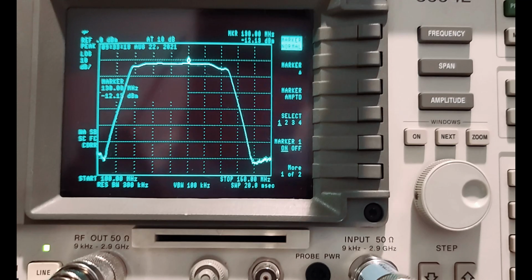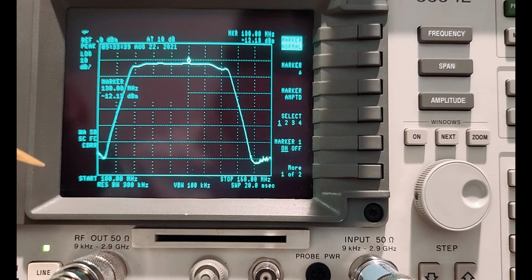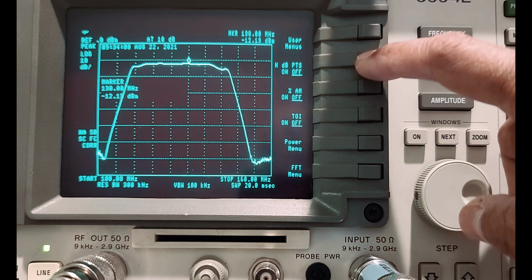dBm. So you might be asking, why is there a negative 12 in this example when we are not using the Rohde and Schwarz sweep generator? Well, the answer is the built-in tracking generator also puts out negative 10 dBm. So by default, that's the amplitude that the built-in tracking generator operates at. So there's an offset of 10 dBm in this behavior. All right, with that said, let's go back to our measurement. We're going to do the same thing, right? Only all of this is real time.